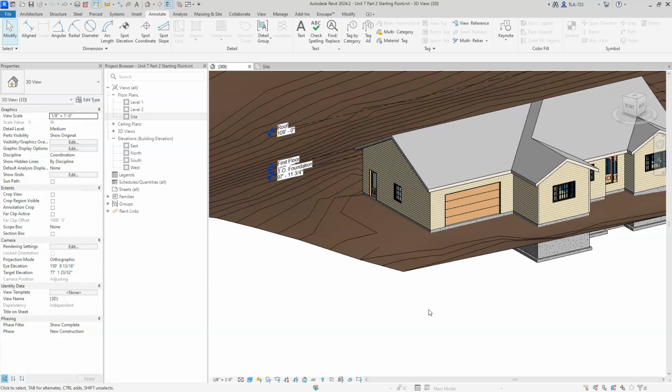It's an as-built model, right? And then we might have to be doing something like putting on an addition or reconfiguring an interior. Maybe in a high-rise office building, for example, we're going to gut the entire interior portion of it and we're going to rebuild it with different shapes and hallways and paths and things like that. In those situations, it's important that we keep track of the phases because we can make them look different and we can also control their visibility separate from one another.